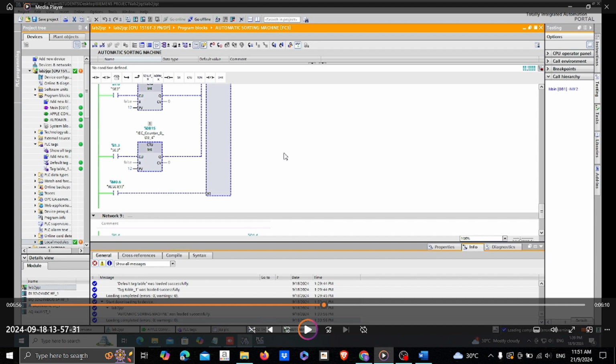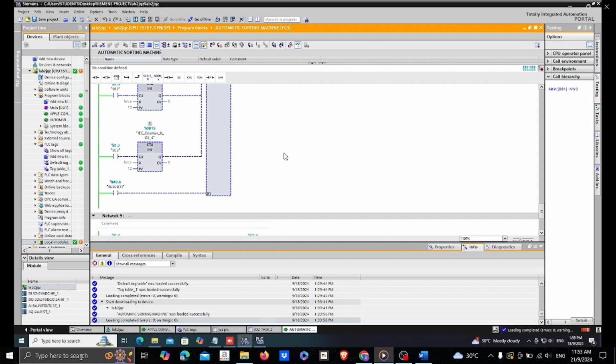Okay, so this circuit is system pausing when count reaches 12. When any of the box categories high, medium or low reaches a total of 12 boxes, the system automatically pauses the sorting operation for that specific category. The system is designed to pause this part of the operation without requiring the operator to press start again. Once the box count for a particular height reaches 12, the operation halts until the operator presses the reset button. Pressing this button resets the counter for the height category, allowing the system to resume sorting.